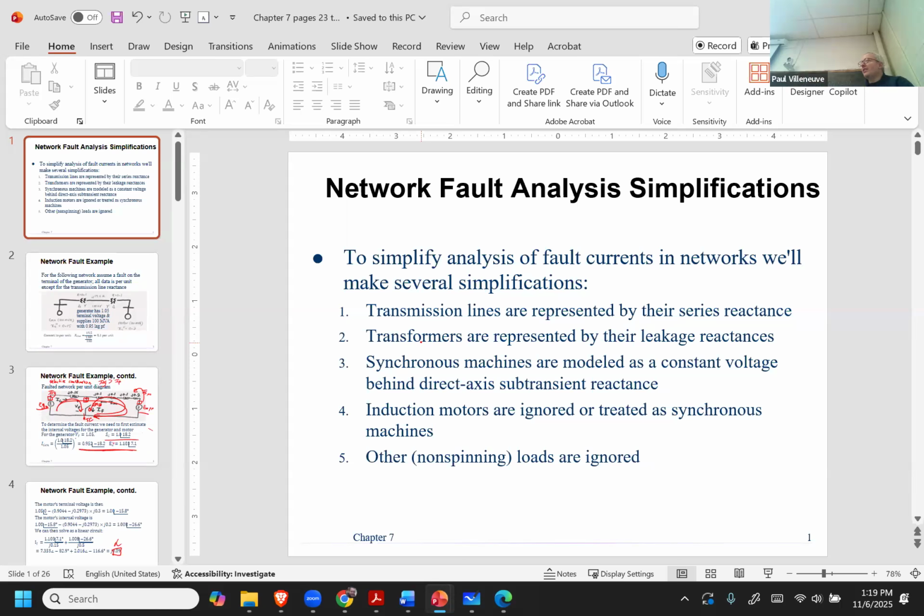It's only when you start getting into more challenging schemes, like when you're looking at volts per hertz. Why is that a concern? Because if my transformer is trying to put up too much voltage for a low frequency, I can actually burn up the windings, even though the current's low. Too much magnetic energy, you can't get there from here. So it's other things that you're trying to protect against. And the distance schemes, you can use current, but it's not nearly as reliable as looking at distance. And even distance is not as reliable as looking at differential schemes.